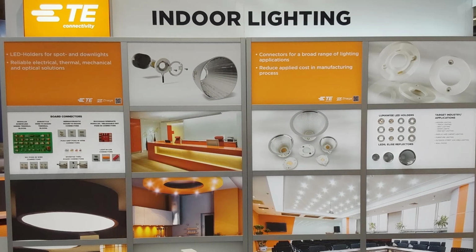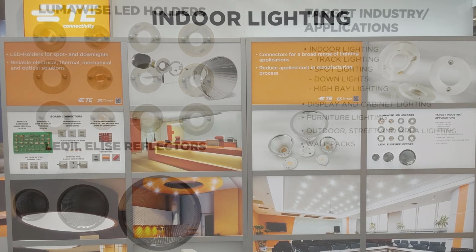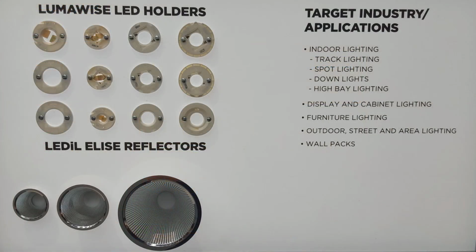So it's pretty simple. You can see how it all snapped together. The sockets are mechanically secure and electrically connect the LED to the luminaire without the need to solder. Sockets allow the LED to be directly attached to a printed circuit board or a heat sink using just standard screws. They have multiple connection points, accept optics, include fast attachment features, and provide proper orientation of the chip.